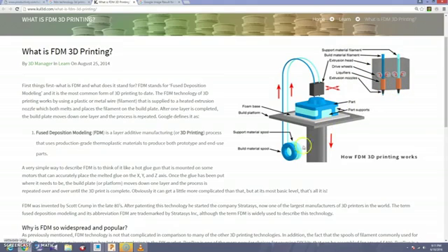Whenever the material feeds in, the platform goes down, and this prints one layer; again the platform goes down, again one layer, and again the platform goes down. This process is continuously repeated. Due to this process we can easily build a part with the use of part material and also support material. So we need one build material spool and one support material spool. This is the basic working process of FDM technology.